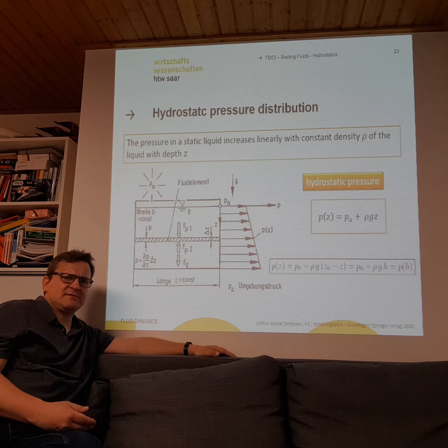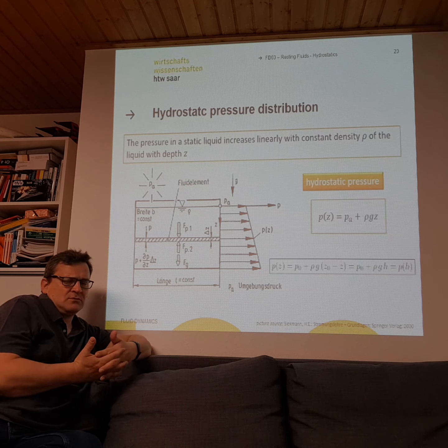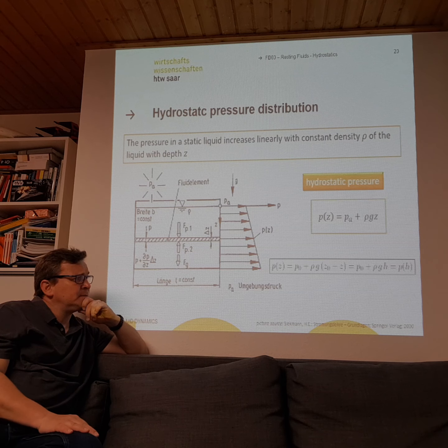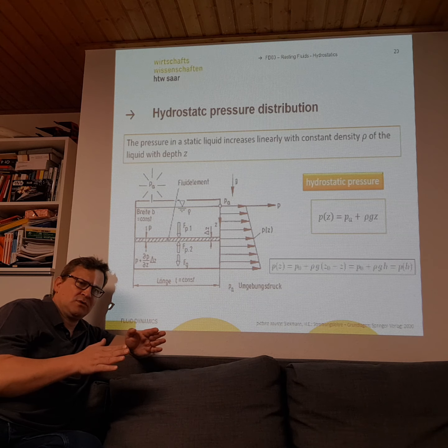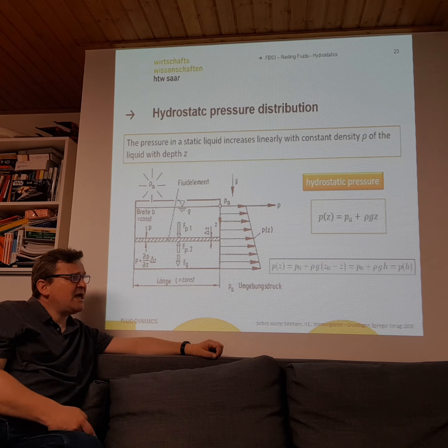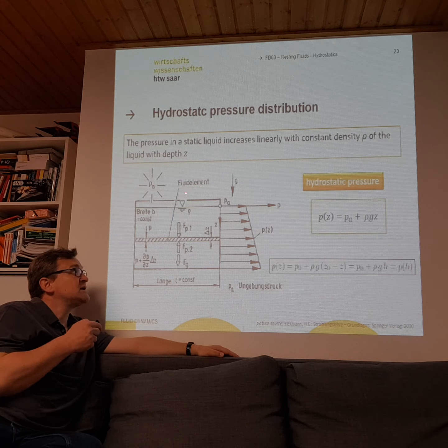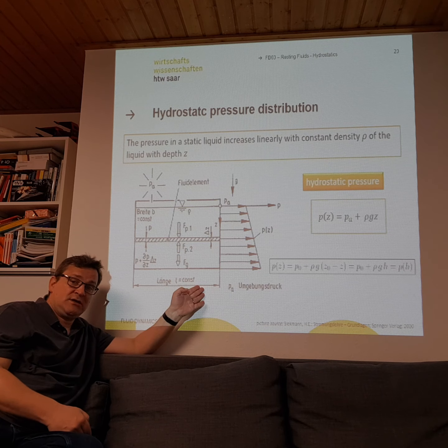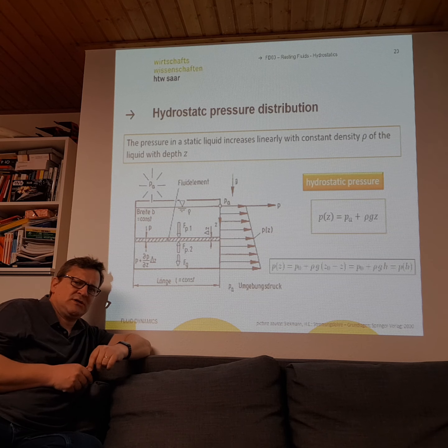Maybe if you have a look at a Dutch dam system, maybe in the next slide I can look for some photos, you will see the wall at the bottom of a dam always has the highest thickness, because there are the highest forces. And there's also another thing. If you make this calculation of the forces inside the fluid, you must always add the pressure that is over the fluid. Here on Earth we have about 1 bar over the fluid, and 1 bar is still a lot.